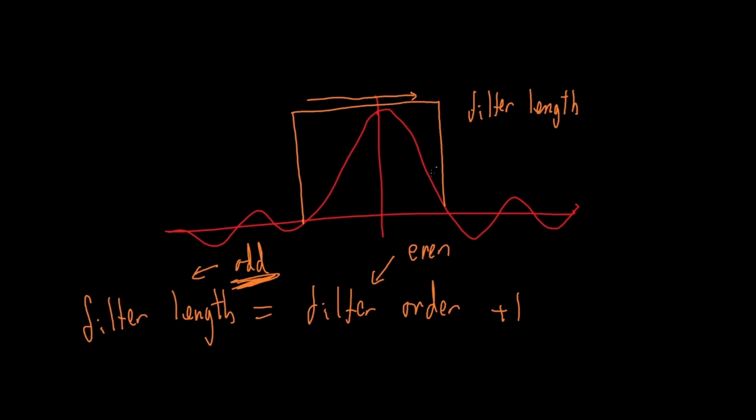By having a longer filter length, you can capture more of the sinc wave, but remember, it's also symmetric, so it must go on both sides. A longer window will have that, and these parts are all the same length. It is a symmetric window all the time. Any window you use is always symmetric.